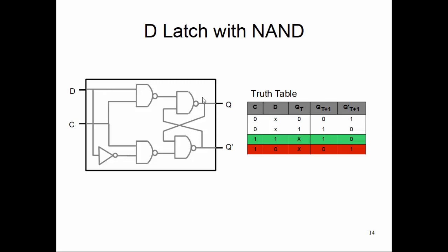We can store it only when C is 1, but with this part, your D logic will immediately reflect onto the output. Remember that output, which was marked as GT in our conception slide, it immediately kind of corrupts the GT and gets a feedback into my combinational part of the circuit. So it's a very risky situation.